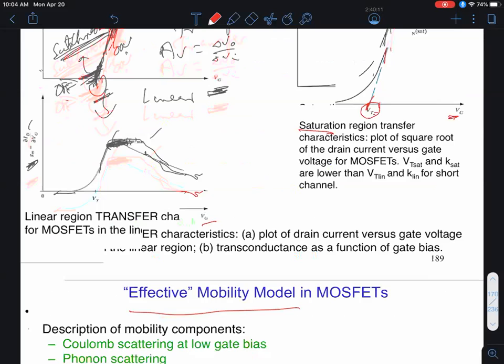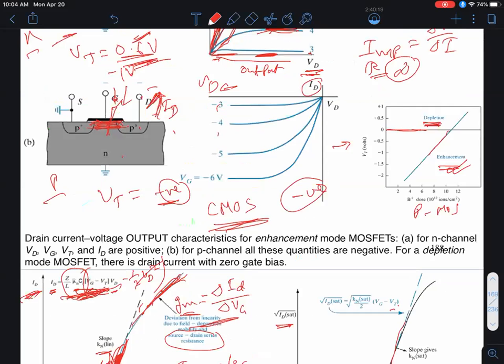If you were to zoom in and take a picture, and these days you can actually do that using very high resolution cross-sectional micrographs from transmission electron microscopy, you'll see that you transition from a nice single crystal silicon structure to an amorphous oxide or hafnium dioxide structure, where you have a lot of dangling bonds, rough interfaces, and so on and so forth.